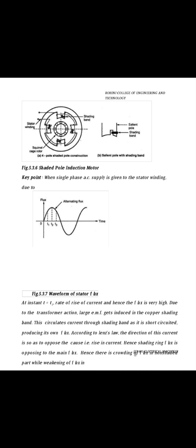Next one is the capacitor run motor. Here, not only the starting but also the running condition performance depends upon the capacitor. Hence, the value of the capacitor is designed as a compromise between the best starting and best running conditions.